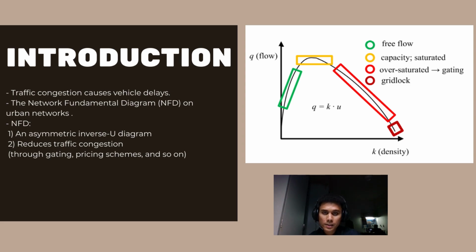The concept of a fundamental diagram, as seen in the structure of a flow density curve in this figure, has recently been demonstrated to be applicable to urban road networks under certain conditions. When network capacity is reached, the traffic flow grows up to the yellow region in the two-dimensional fundamental graphic. When the critical density limit of the system is reached, it begins to deteriorate and finally enters the oversaturated area, the red zone.